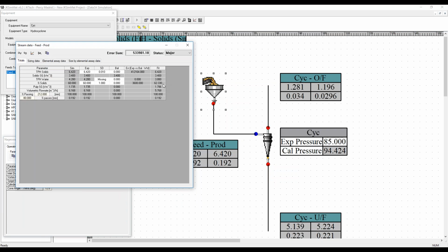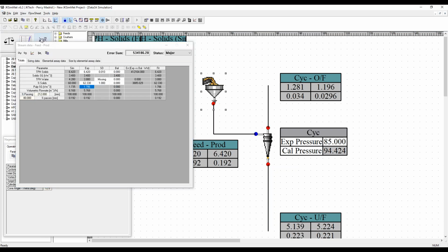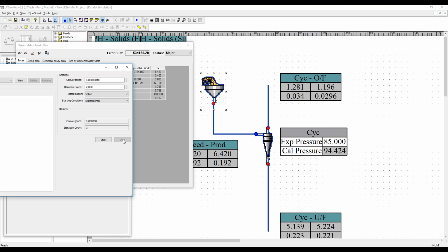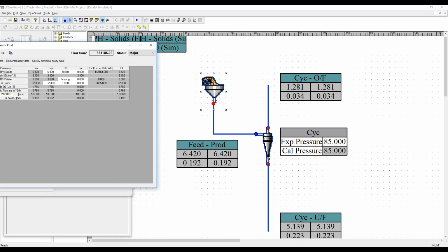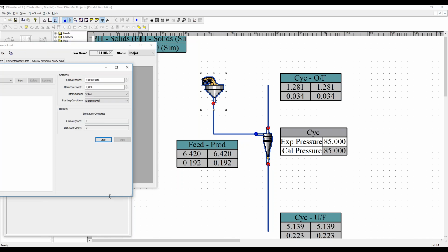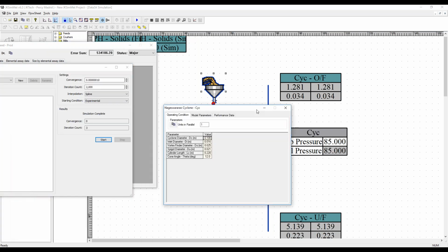For example, I can go back on the percent solids like that, and I run a simulation. So I just went back to the original percent solids. So you can see numbers are the same in both columns of each info block, which means this is a starting point again. So I will run now another simulation, just changing, say, spigot diameter.